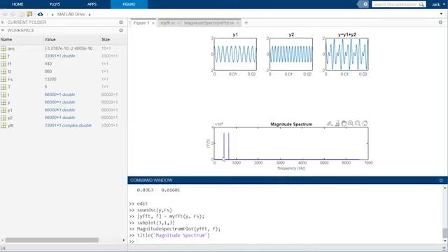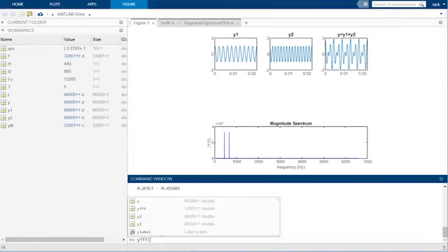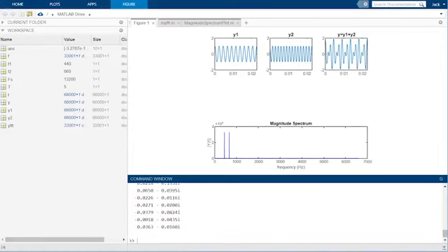We can see that our plot function has plotted the magnitude spectrum, which shows the Fourier components to all be zero, except for at two frequencies, which correspond to 440 Hz and 660 Hz. The magnitude of the Fourier components are zero everywhere except for these two frequencies. For example, looking at the first 10 components, we see that we get numbers with magnitude on the order of 10 to the minus 9, which are consistent with floating point round-off errors.